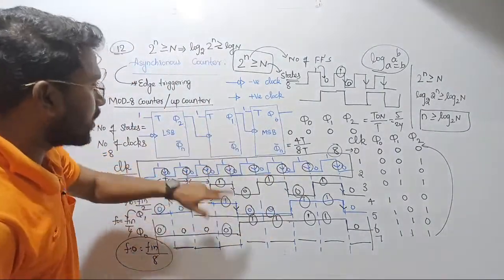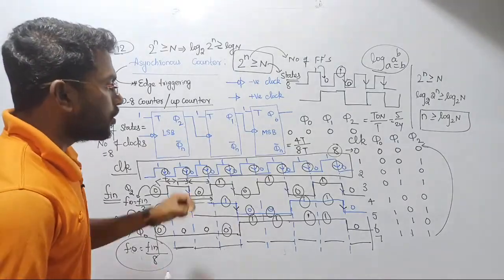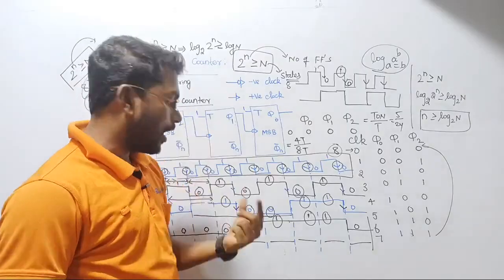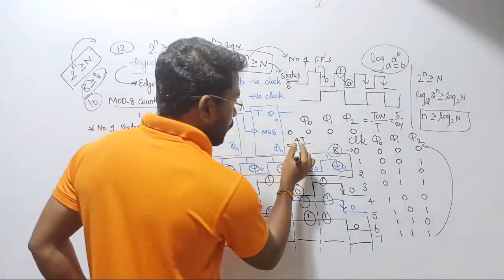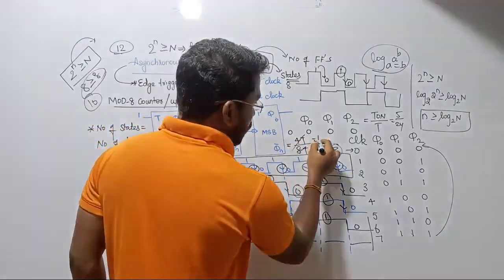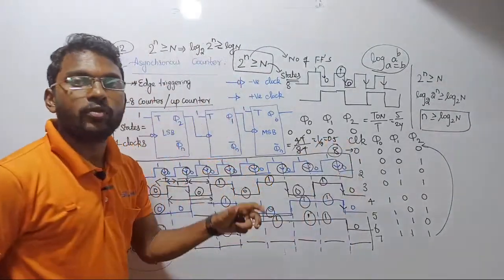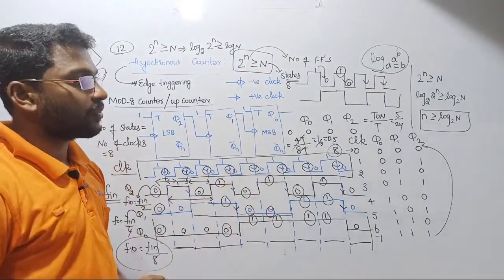You can also check it for this one like this. So duty cycle in the sense, on time divided by total time. On time denotes the pin is high, output is 1. So totally we are considering 4t. If I cancel it, what does it become? 1 by 2, or 0.5. In percentage, that is called 50%. So duty cycle is 50%.